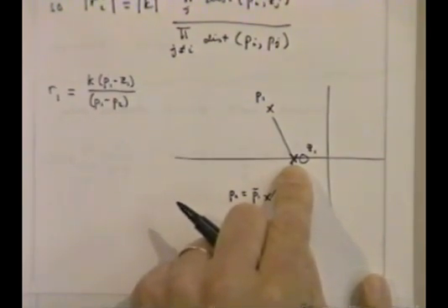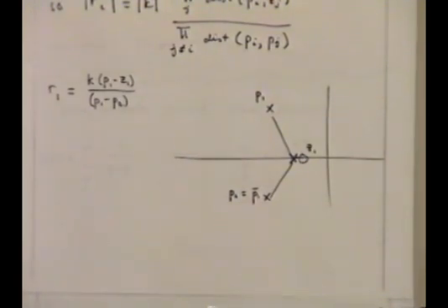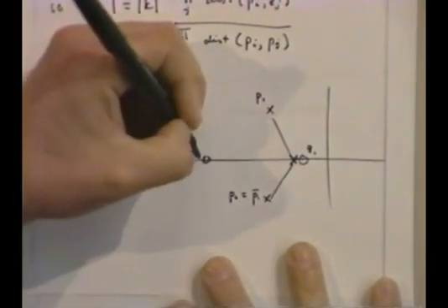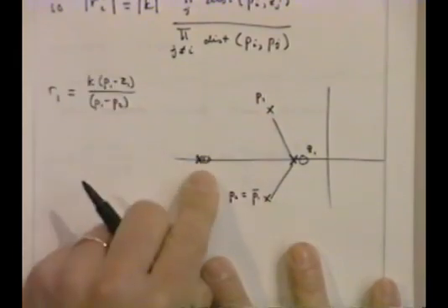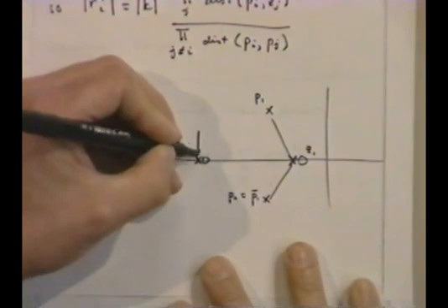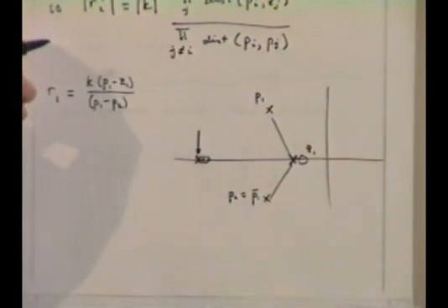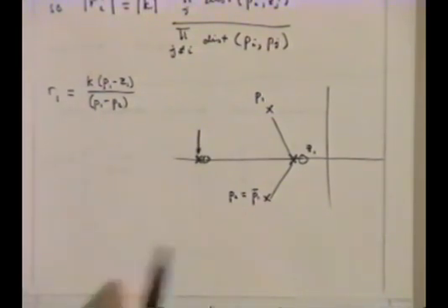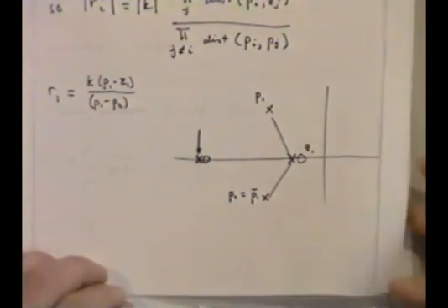Okay? This actually makes perfect sense if you think about it, because if I walked up to you and said, here's my transfer function, and I've got this pole and this zero like that, you'd say, well, they almost cancel each other. And in fact, that would come out in the time domain because the residue of this pole would be really small. And so whether or not you could neglect it depends on how small that residue is. So that, again, makes sense. Okay, so this was one connection.